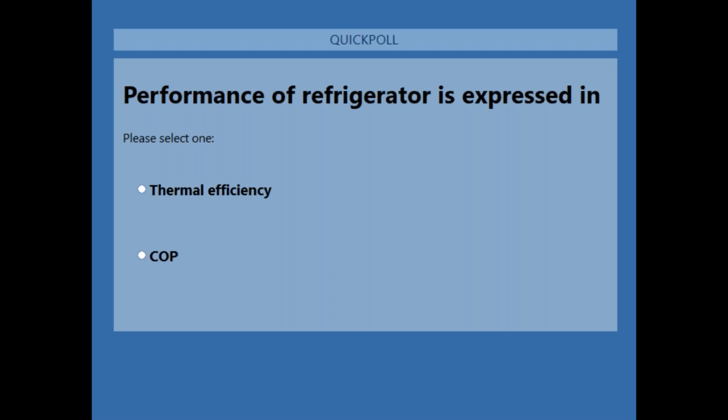Then we have looked into the Clausius statement of second law, which talks about the impossibility of constructing a device which would pump the heat from a lower temperature to a higher temperature without any work input. It tells you that you cannot construct a refrigerator which would not consume any electricity. So if you want a refrigerator which pumps the heat from a lower temperature to a higher temperature, then we should be expending certain work. In your household refrigerator, that work is expended in the compressor, where you are giving certain work so that there is a pumping of heat from a lower temperature to higher temperature.